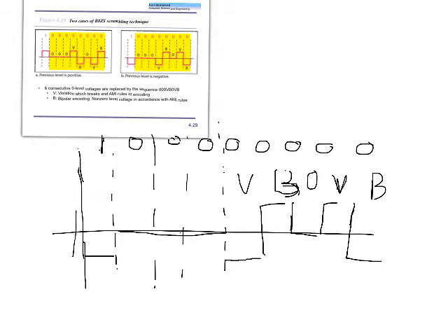So when the receiver reads that, it will find that the previous voltage level was negative. Okay? Here the previous voltage level was negative, and this is also negative, so this is not the normal procedure of AMI. This is the start of scrambling. So it will interpret all these bits as 0 and not anything else.